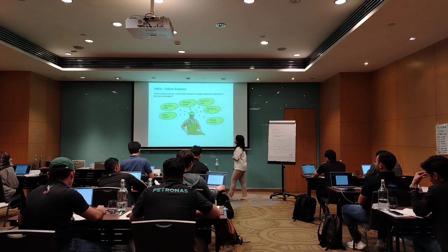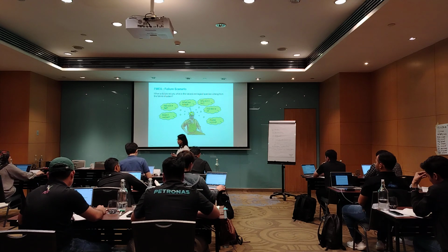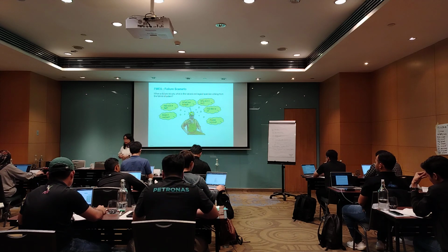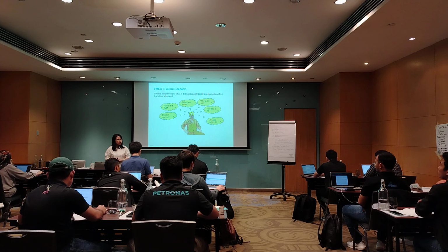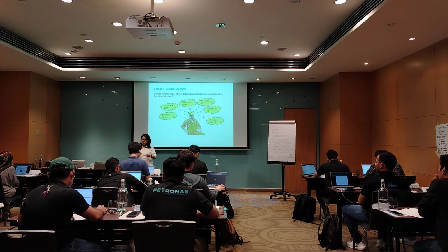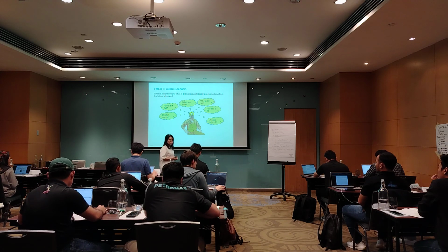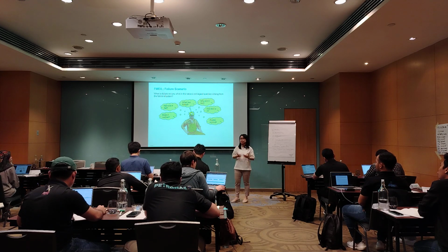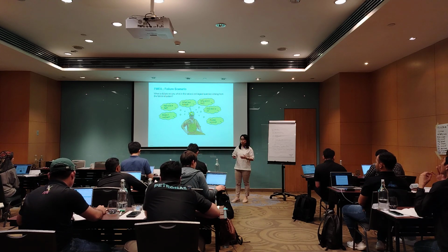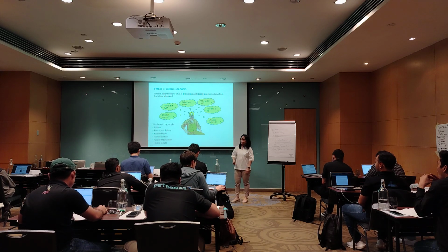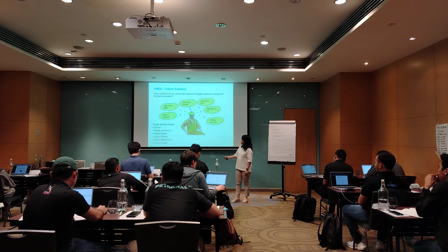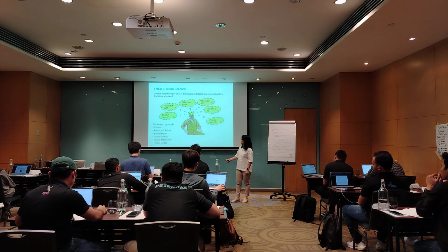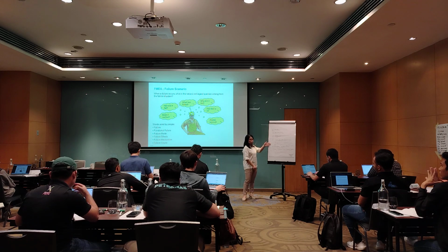Alright, so FMEA, you need to ask this kind of question. When you are facilitating the FMEA, you need to ask about the function, what kind of functions, how does it fail. When it's failed, it doesn't really matter, or I just change it, do not have any consequences, right? So there's kind of questions. How bad is it if this is already failed? Do I have another redundancy? Okay, so normally people use functional failure, failure mode, failure effect, failure mechanism, and failure causes, which are already derived for you. Okay?